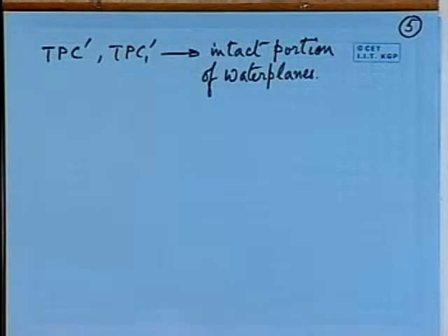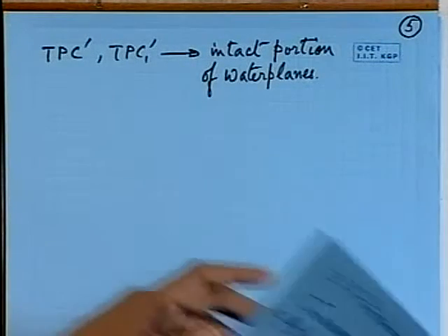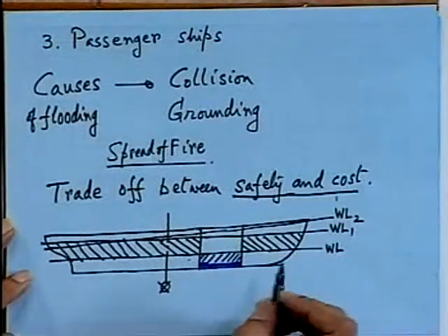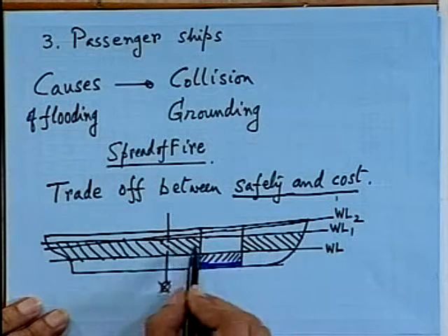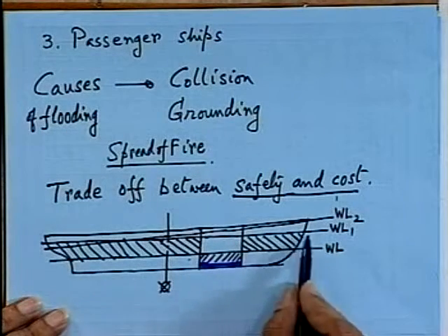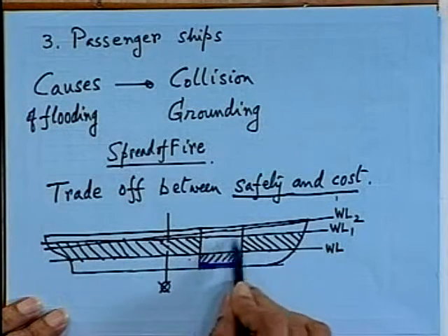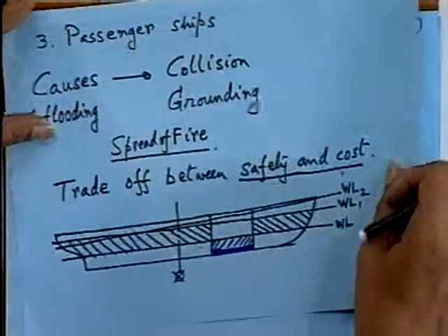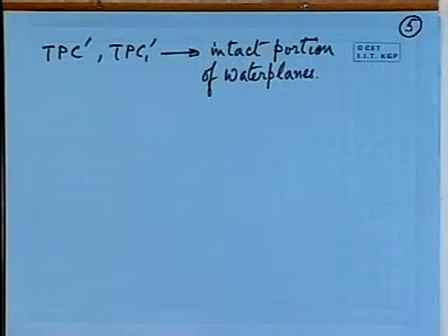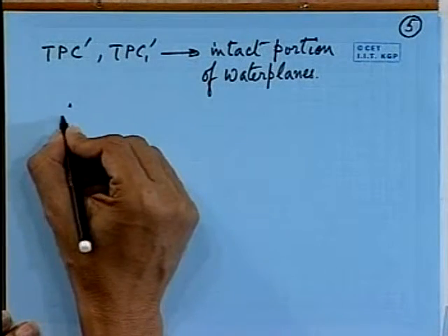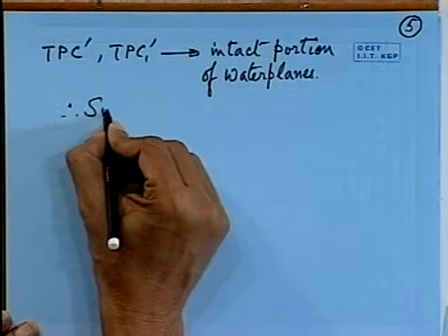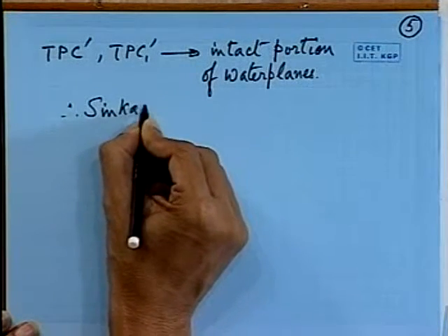Intact portion is, again, I am just telling this again, such that this is your intact portion, this one, this one. You leave out this damaged compartment. So sinkage, in terms of TPC, we have to calculate.